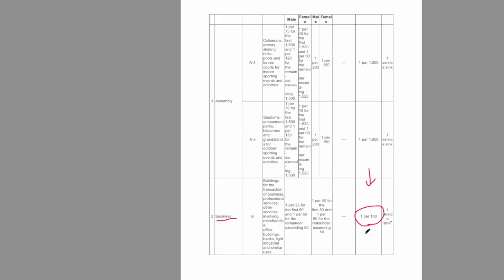The number of drinking fountains, the number of bathrooms, the number of water closets, all that stuff has to work for whoever moves into the building. So the scale of the building and the occupancy, those two pieces of information are the thing that we would actually really need to think about.